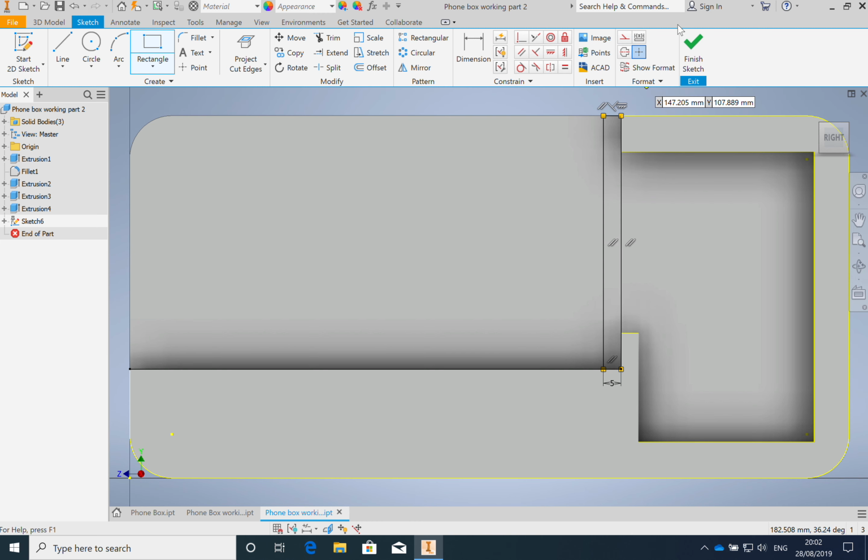Okay, with that done, you next want to select a line, come down to the bottom left of this rectangle, click once and let go, and you can see you've got this line. If you click and drag, it will give you a curvy line. We don't want that, so click and let go, and then just move it so that you've got a nice horizontal line. I can see that by the degrees there, it's horizontal. And I want this to be 8mm. So I'm just going to tap 8 and press return. And then to get out of this line, just press escape on your keyboard.